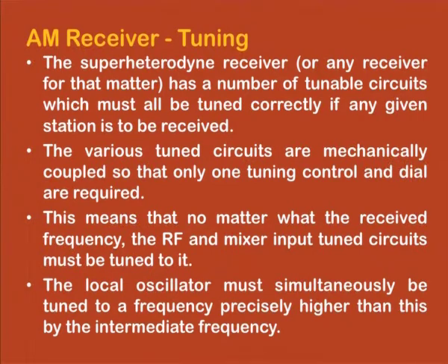The most important thing we need to talk about here is the tuning of an AM receiver. A superheterodyne receiver, or for that matter any receiver, has a number of tunable circuits which must all be tuned correctly if any given station is to be received. The various tuned circuits are mechanically coupled so that only one tuning control and dial are required.